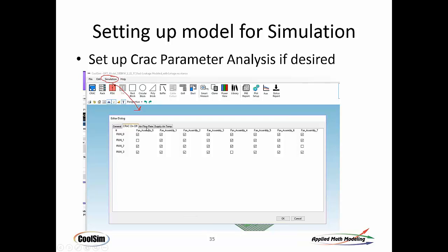And you can't see it, but under airflow and temp, I would set those parameters accordingly as well. So in this run, we're assuming that VFDs are in effect, and what would happen is in run 0, they'd all be running fairly slow. In run 1, you'd have to ramp these others up to compensate for this guy being down, etc.